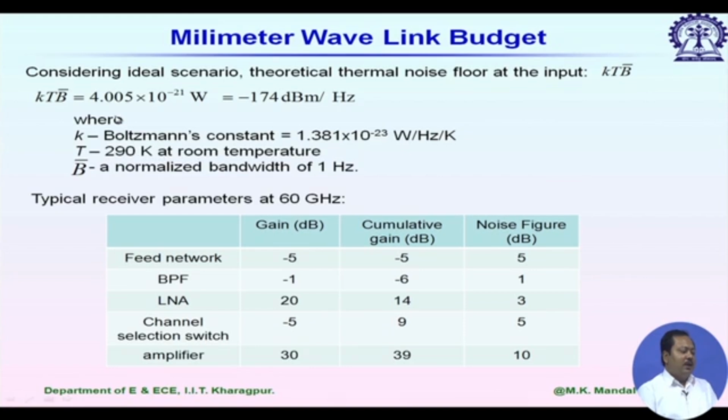Putting the values here, it comes to 4.005 into 10 to the power minus 21 watt per hertz, and if I convert it to the decibel scale, it is minus 174 dBm per hertz.